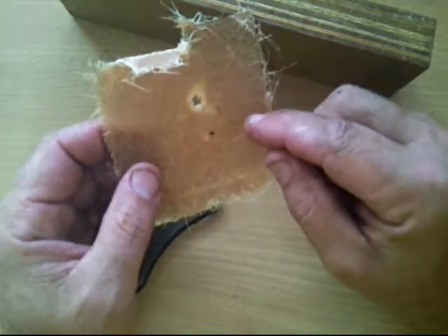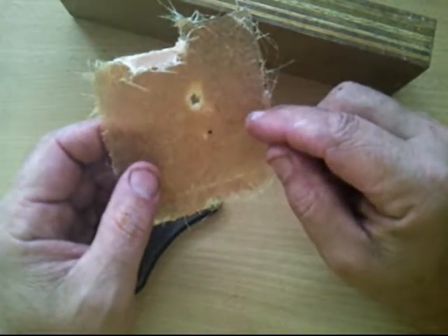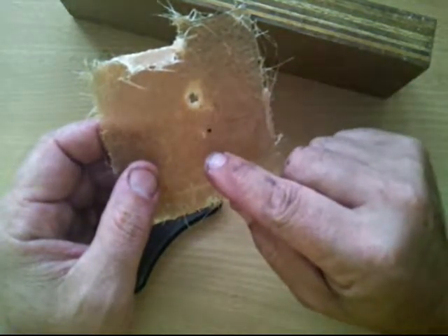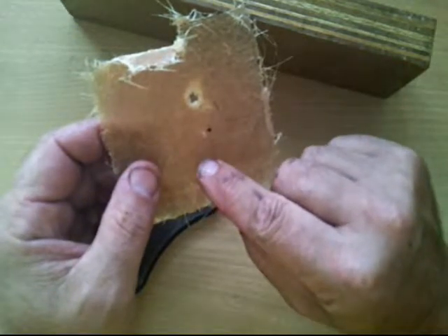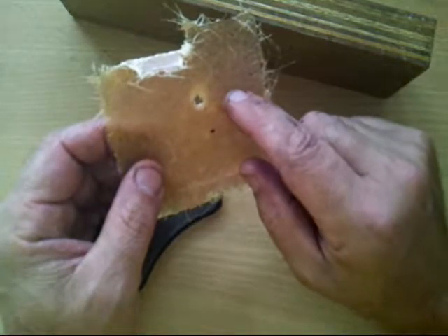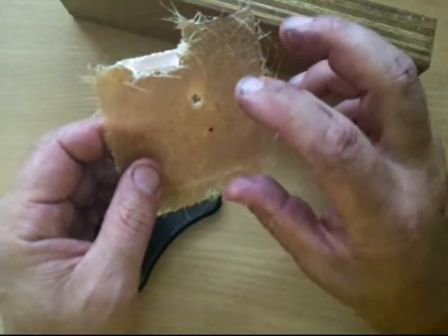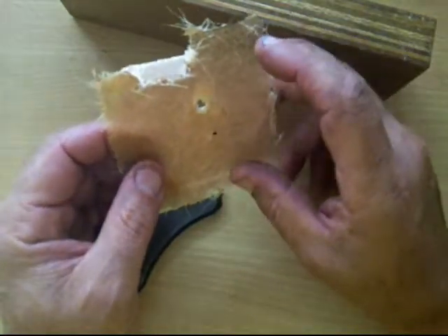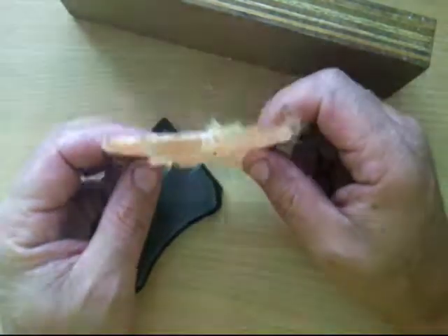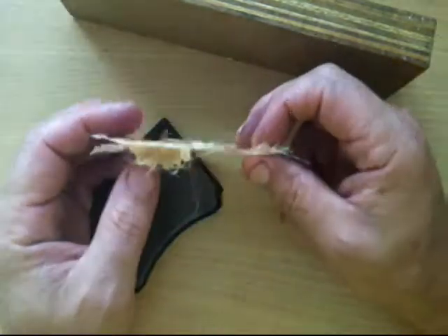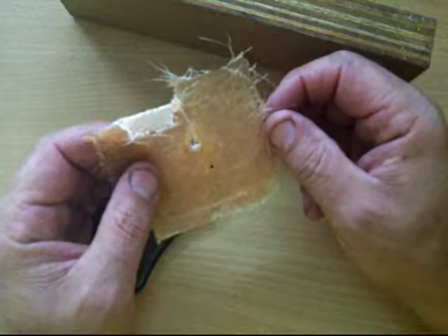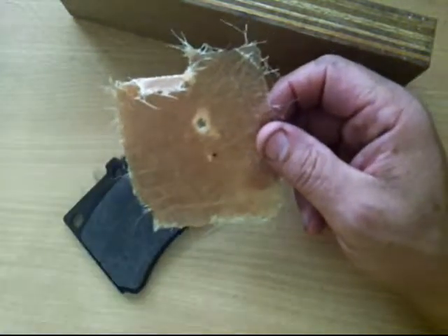The reinforcements are held together and used by the matrix, and the matrix allows a transfer of force to go from outside the object onto the filler portions. So essentially it holds it all together. The matrix provides bulk, it can provide some heat resistance or thermal stability properties if those are desired, and then it allows force to be transferred onto the main load bearing structure, which is the filler.